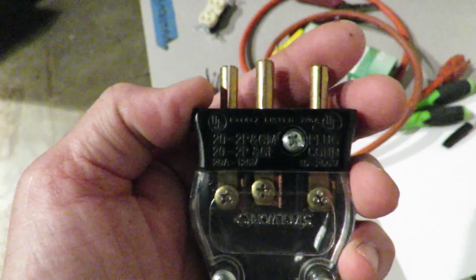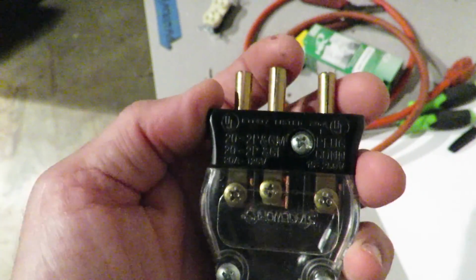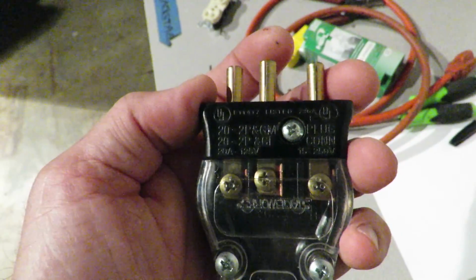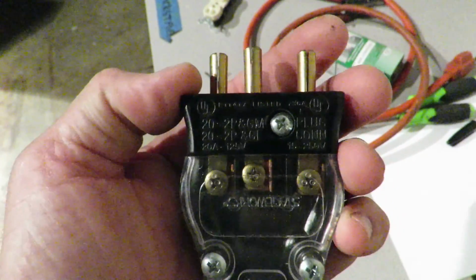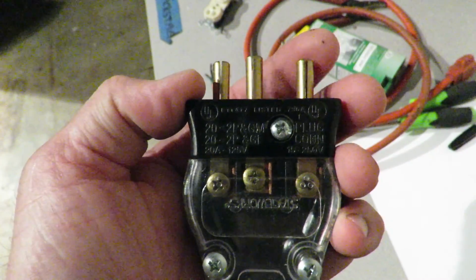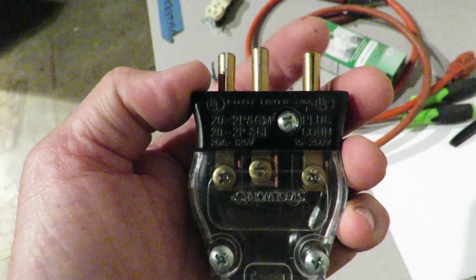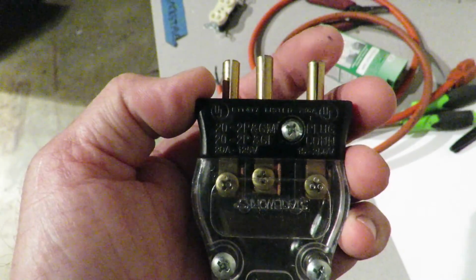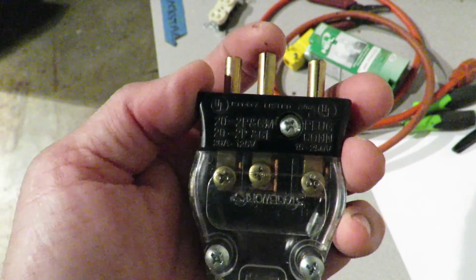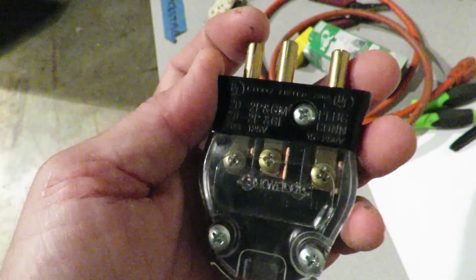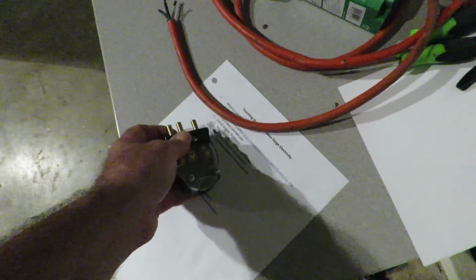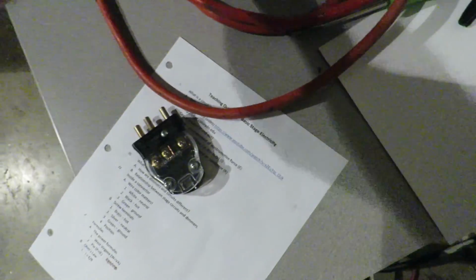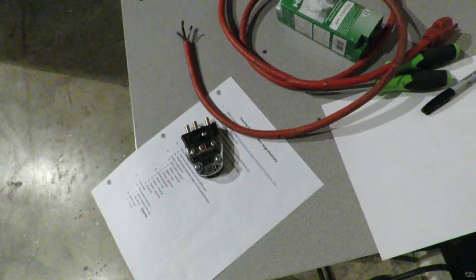You'd take the hot off first, then the white, and then the ground is what you would take off last. So just remember, the black or the hot wire goes off by itself on this isolated pin here. The green is always in the middle, and the white goes on the one that's left over. You'll find that the exact same thing is true whether you're doing a